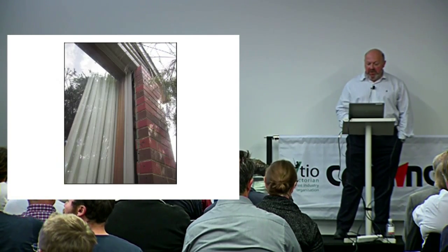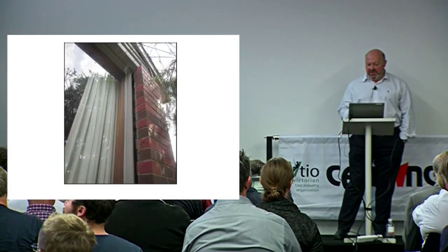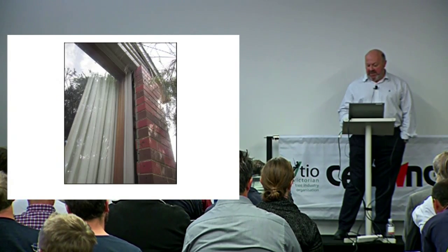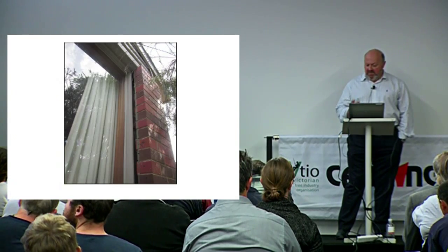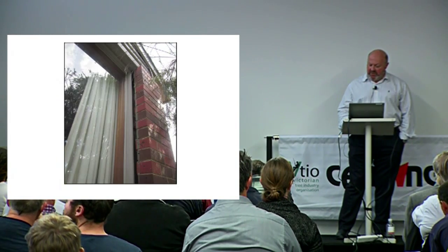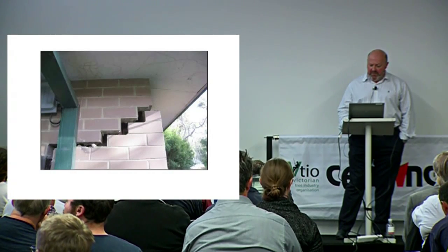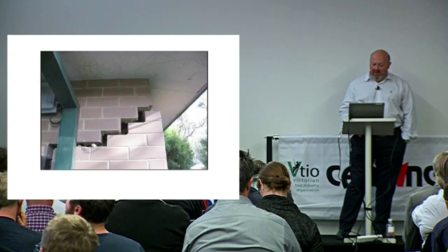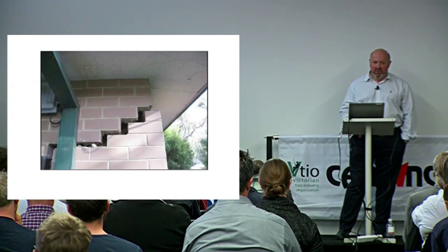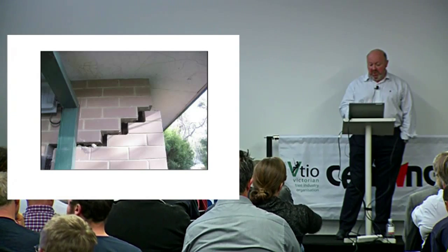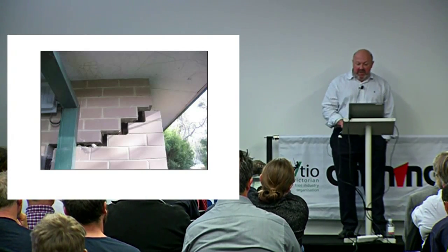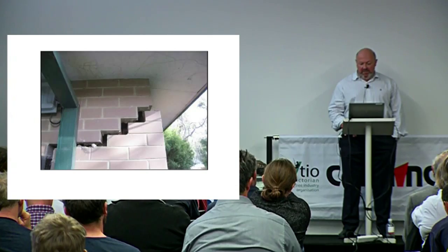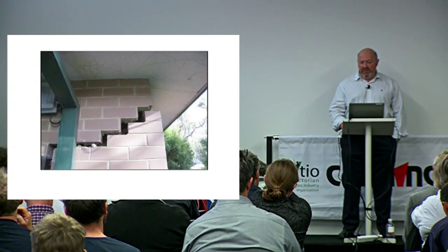This is the same house I showed you with all the trees at the front, which just goes to show the principle can't be applied both ways. So the back of the house is rotating off, and the soil's super dry, full of tree roots. That was a fairly significant drying issue as well. That's probably at the upper end, the category 4 crack. But again, we tested the soil directly underneath that point and it had plenty of bearing capacity. It was probably 15 percentage points, maybe 12 percentage points under the plastic limit, so really, really dry.